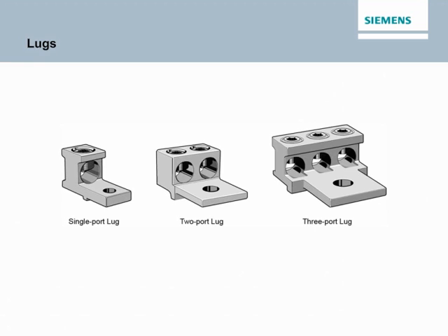Stud terminals accept either lugs or compression fittings. Common uses for the studs include applications where the field wiring may be either single or parallel. Terminals may be mixed on the side or on the line and load sides. For example, a socket can have studs on the line side and lay-in lugs on the load side.